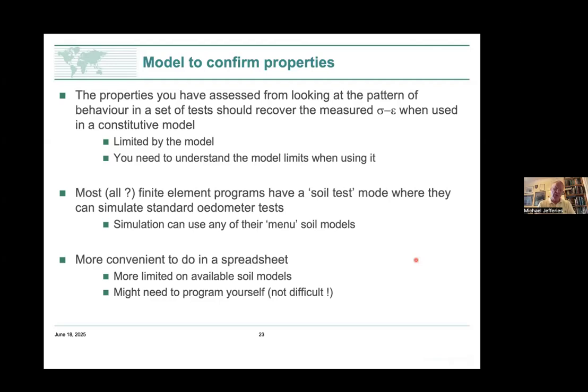So you can work your way around a stress strain curve by saying, okay, I'm at a strain of, say, 3.5%. What is my G and K at that strain? Okay, I'll now step out by increasing the strain by 0.1%, and I can use that G and K to predict my new stress state. So you can work your way around a stress strain curve.